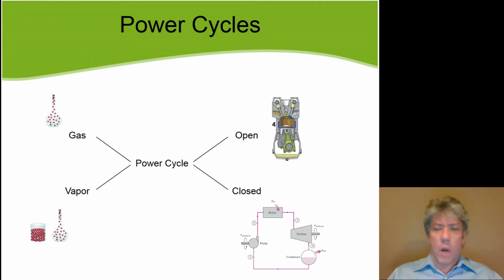So why is this called an open power cycle? It's called an open power cycle because ultimately the working fluid comes in and then leaves. So it's not so much the process itself and whether that process is open or closed, but whether or not the working fluid ultimately flows in and then out of the engine. Of course, that's the case here. The air that comes in your intake ultimately goes out as exhaust, having been changed somewhat. Temperature, chemical composition, and so forth. So that's why it's called an open cycle, because the working fluid enters and then leaves.